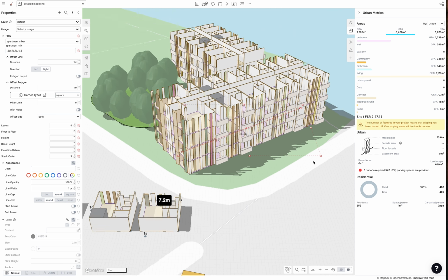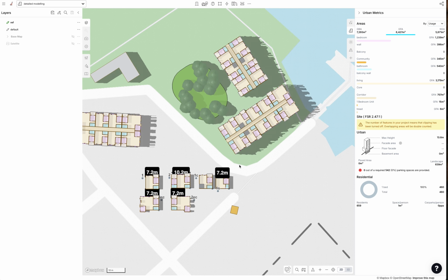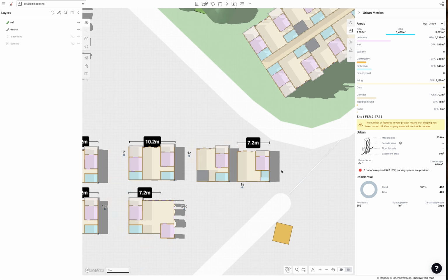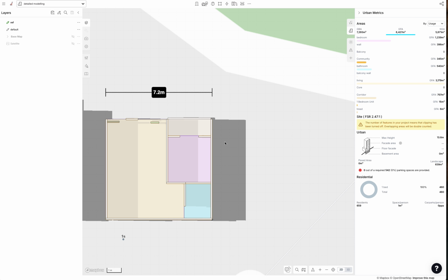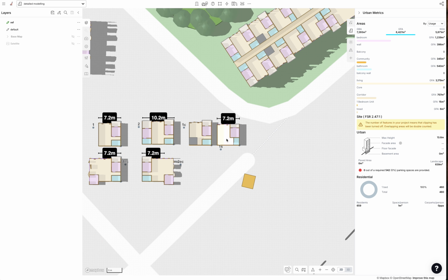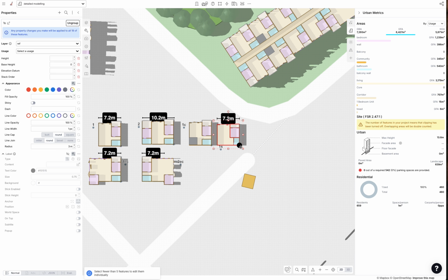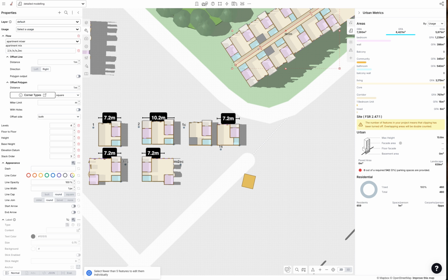It just ends. So in this video, what have I done? I have shown you how to draft precisely using snaps, keyboard input, the grid, and then I've shown you how to add this block with block base point to this flow. And how I made that flow is in another video.